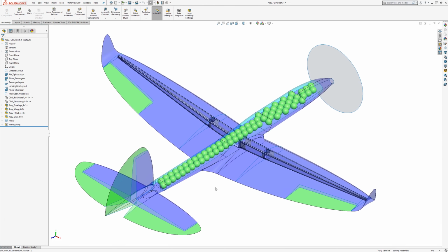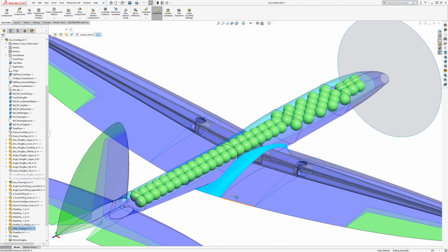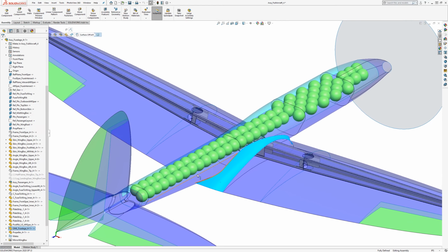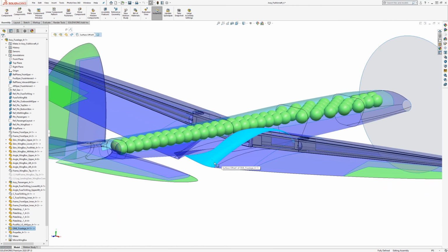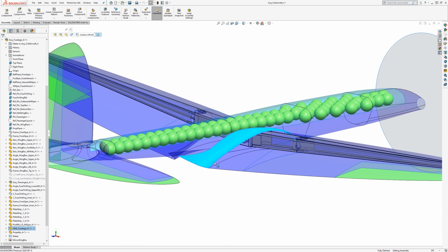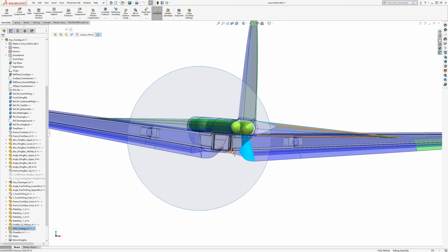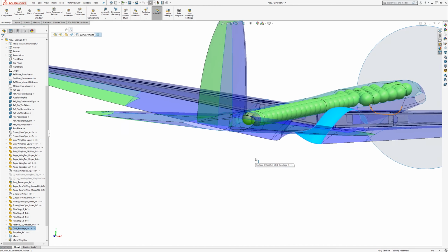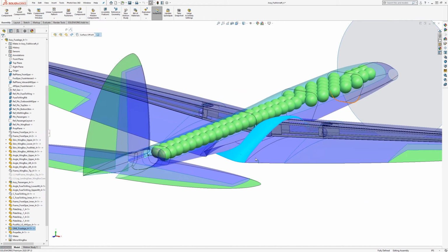Now for the wing root fillet, there are lots of ways you could blend the surfacing between the wing and the fuselage. It's going to depend a lot on the shape of your wing and your fuselage, the camber of the airfoil, and the angle of incidence of the wing, and also whether it's a low wing or a mid wing or a high wing, especially for where that trailing edge ends up, how much lower it ends up than the fuselage.